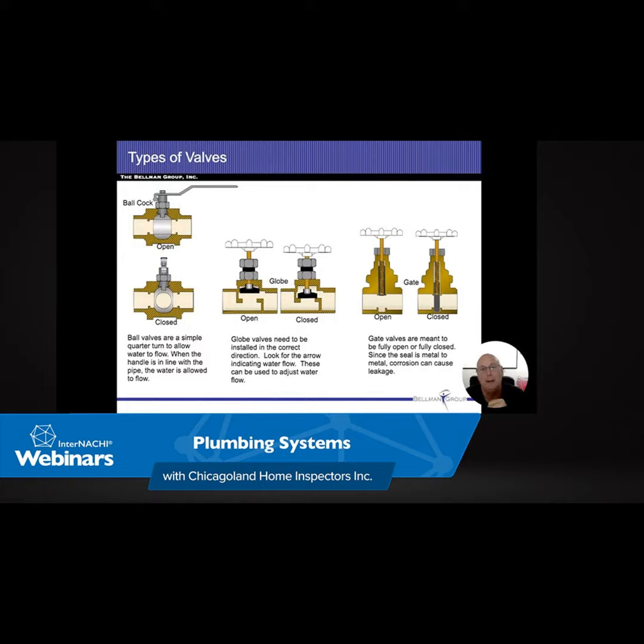Common sense stuff, we don't want to put a soil stack next to a window. This happened to be in Elgin as well. We were doing field training out there, and this was not the house that we were inspecting. This was actually the neighbor's house, and down below they put that addition on, and they put a bathroom in the addition, and instead of going to the left or the right of that window, they just went above the roof line and stopped it right there, and that would be it.